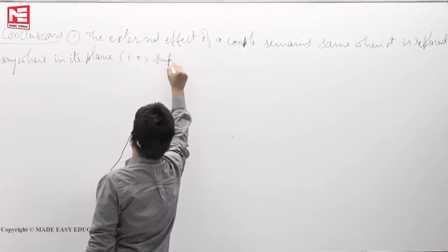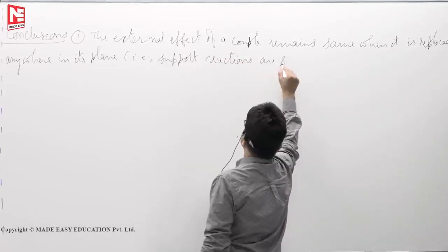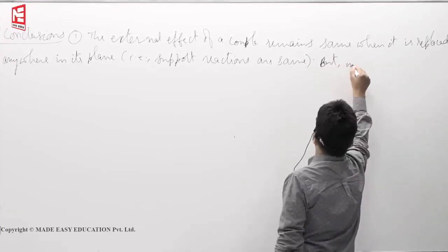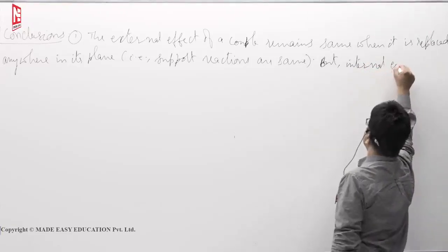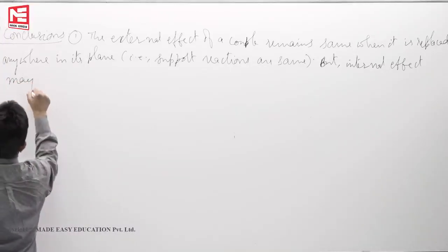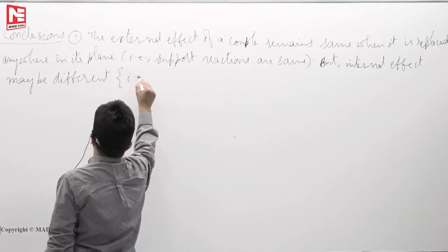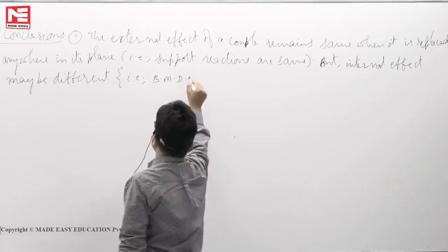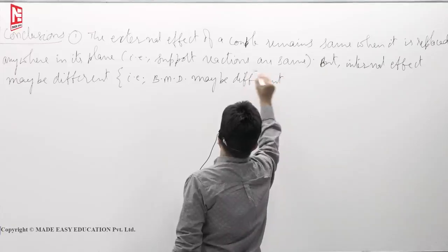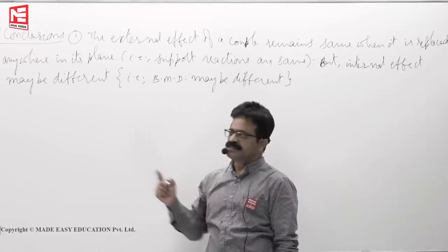That is, support reactions are same, but internal effect may be different. That is, bending moment diagram may be different. That's the first observation. Once in one of the civil services exams they asked that observation.